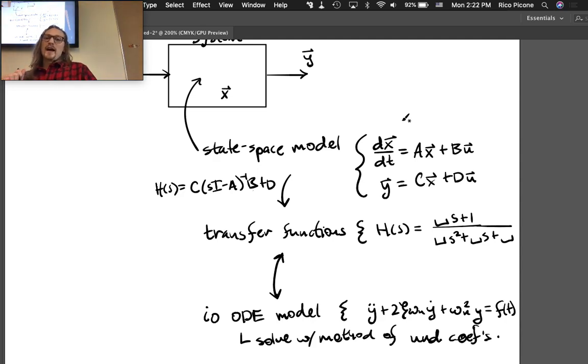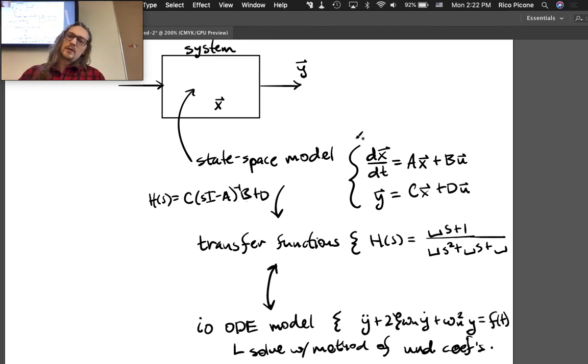And when we do that, we're going to have to linearize this. Or I guess I shouldn't say we have to. It's much easier to solve the system if you linearize it, meaning that the A matrix is a diagonal matrix. You can do that by transforming the state variables, the state vector, into a new basis, a very special basis that diagonalizes the A matrix.